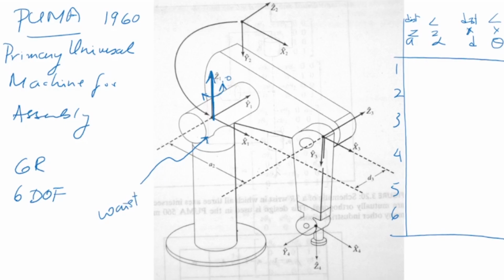If you're standing on this side of the robot, that is your left hand, if you can imagine it that way. And this is your waist here now. And your waist axis is a vertical axis. So Z0, Z1 is marked here. Now Z2 is this axis which is called the shoulder. It's like the arm can go up and the arm can go down. This is the shoulder axis, and this is my Z2 axis.